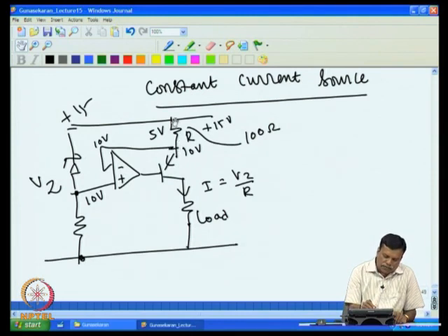So then the current flowing through this will reduce. If the current flowing through this reduces, then voltage at this point will increase, because if this is 15, the voltage minus the voltage drop across this is the voltage that you are getting here. So if less current flows, you have less voltage drop. So this voltage will go towards 15. For example, 0 current flows, this is 15, this is also 15. As current increases, this voltage decreases. So current decreases means this voltage will increase.